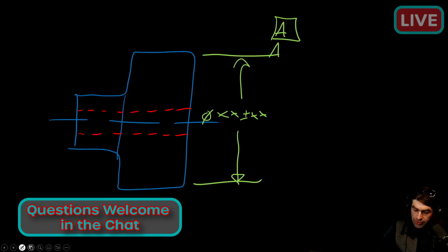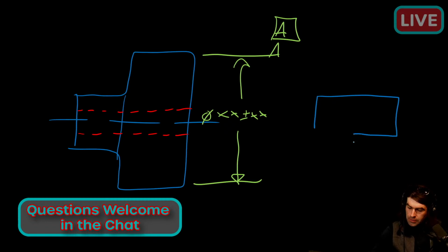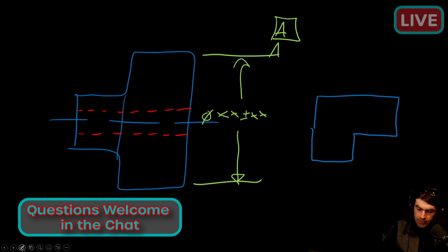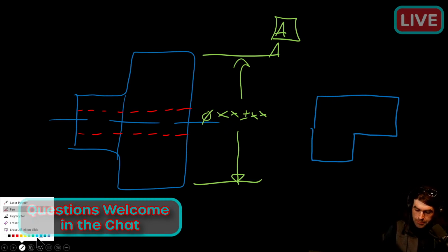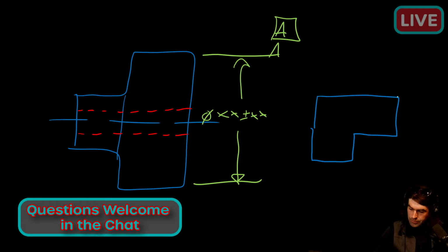Typically, if this was a square part, some kind of rectangle, and we put the datum feature symbol not in line with the dimension, it applies to the surface.